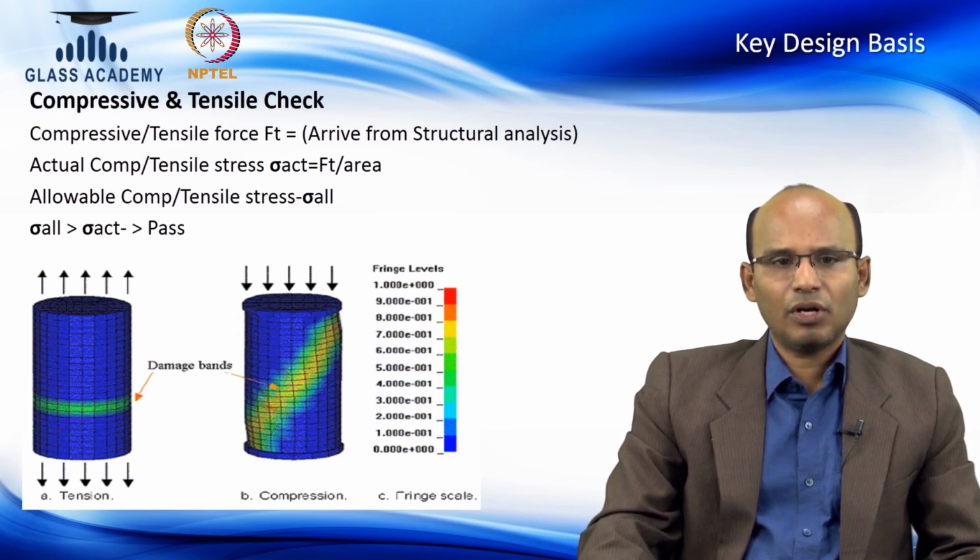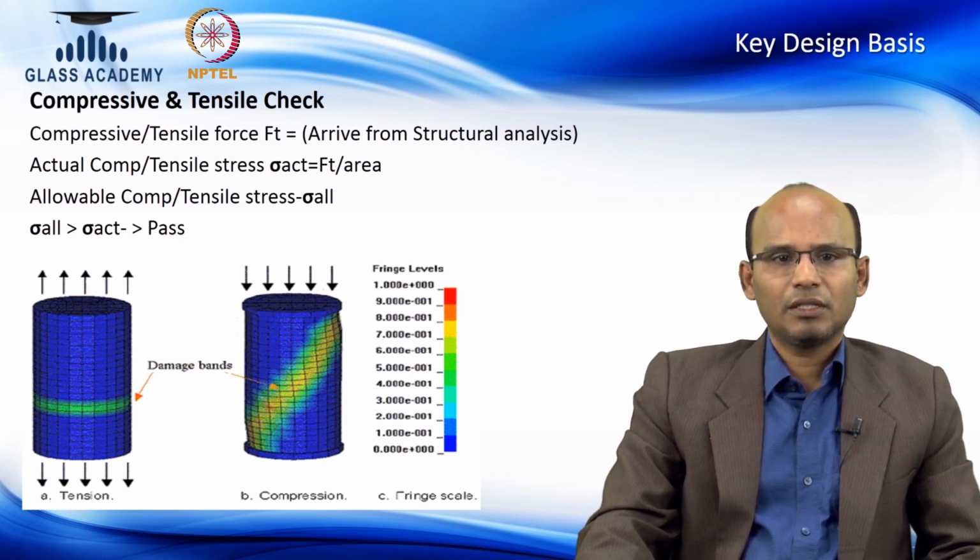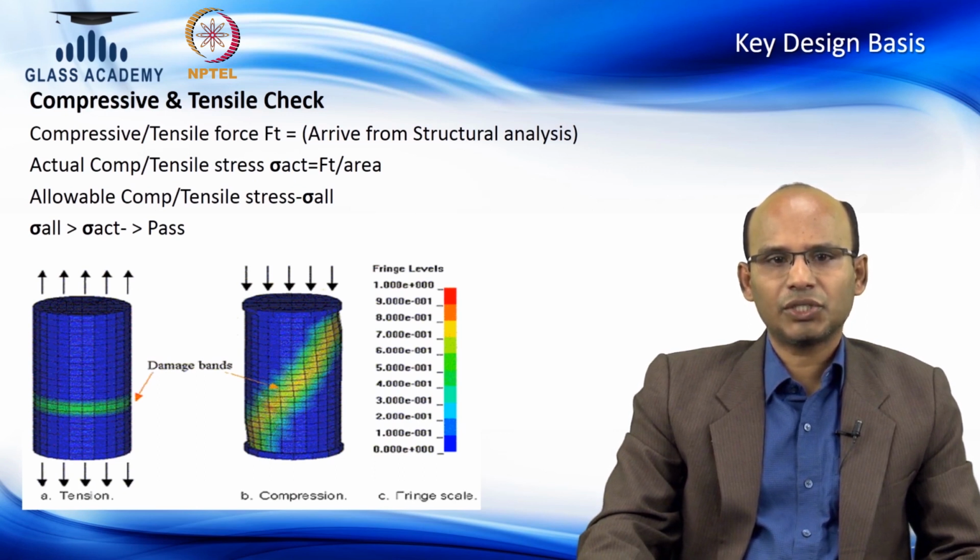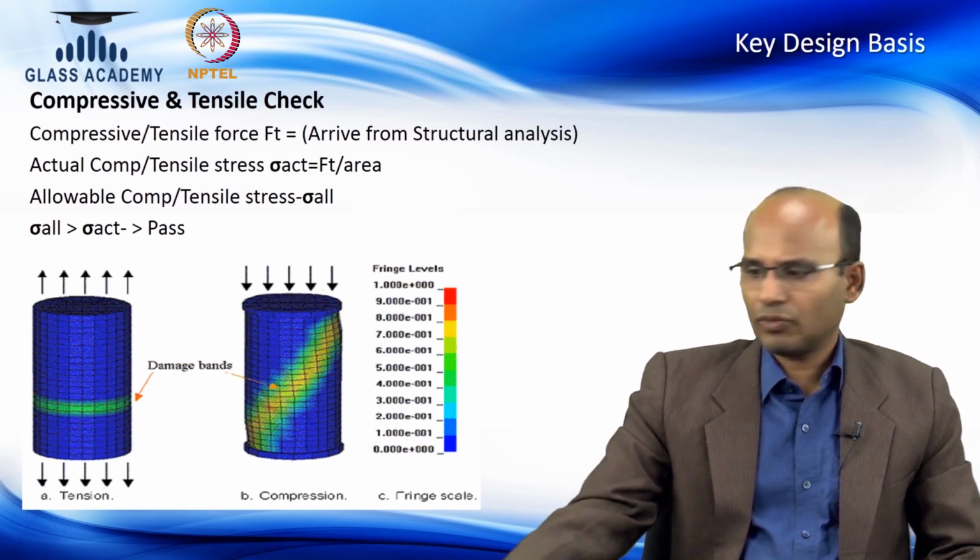This is critical for a large element, or maybe sometimes the framing is used continuously for quite a number of floors. There, compression is critical. As a structural engineer knows, when certain elements are weak in slenderness ratio, engineers have to check the slenderness ratio. If that falls under semi-compact or slender, then this more detailed check is required.